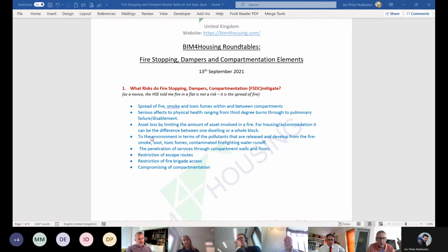But the point is you will need this, because if you start putting ducts into flats, then you will need to protect them. The other point that I made in my email was that if you have a common extract system, which a lot of places, certainly older buildings, do, then essentially they link all the apartments. So all those extract shafts and ducts, toilet extract, bathroom extract, if they're not going straight to outside, then they are ducts and they will need protecting with dampers. So you've got two things: ventilation going in that may arrive, but also extract systems that could well be there even now. Excellent. And we've got that in your email.